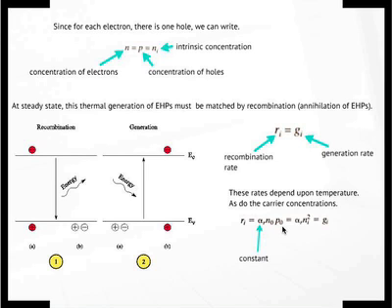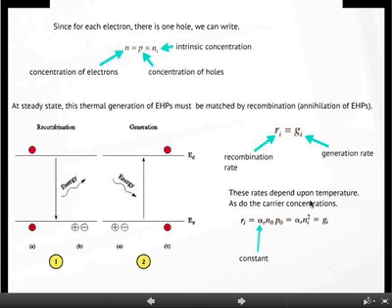which makes sense, right? If you think about it, we'll come back to this. If you think about it, the probability of an electron hole pair generation depends on how many electrons are actually there in the valence band first, right? If there are more electrons in the valence band, there's a higher probability some of them will get excited. So it has to depend on the carriers that are already present. Okay? That is this side, Ni squared.